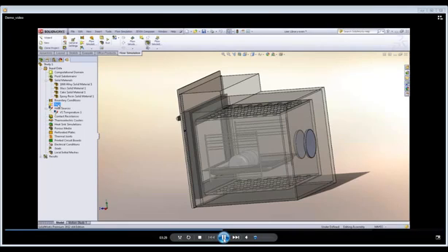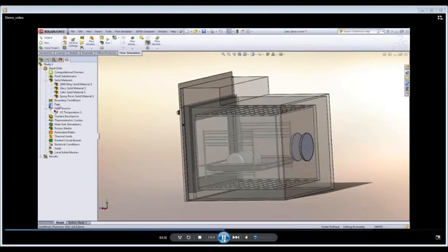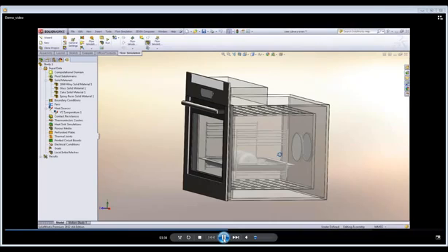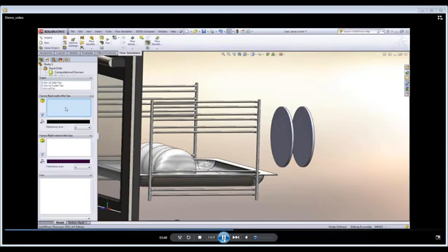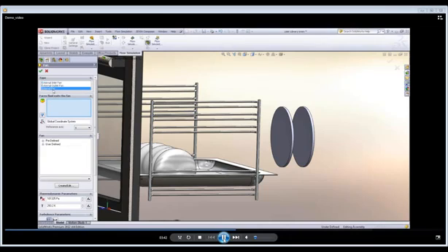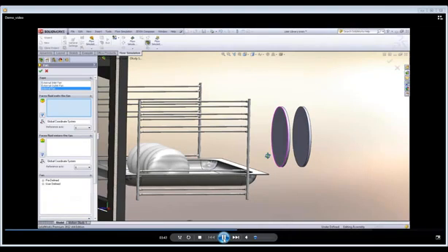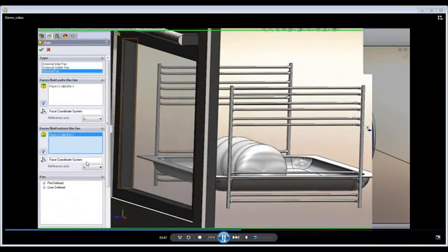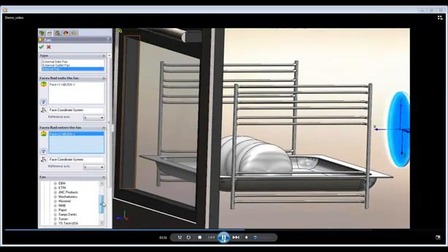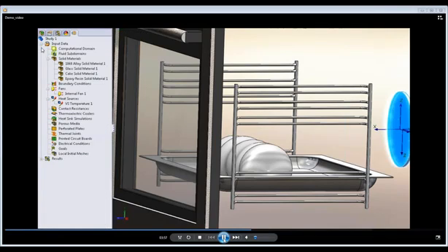As we are modeling this oven as a fan-assisted oven, we specify the correct fan. The fan is located at the rear of the cooking volume, just here. And an internal fan will then be applied to simulate the effect of the fan without modeling it in full detail. So we'll select here an internal fan in Flow Simulation. And the fan curve can be picked out of the pre-installed SolidWorks Flow Simulation library, as you can see now, or imported from a user database.